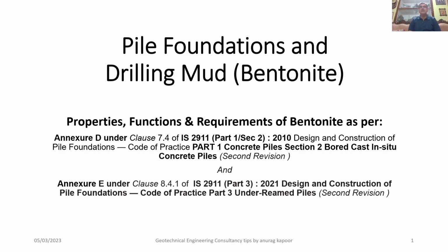Today I will be discussing with you all about pile foundations and drilling mud bentonite. That is, whenever we cast pile foundations in sand under water, we have to use bentonite for stability of the drilled borehole so that the further concreting can be done into that particular drilled borehole.